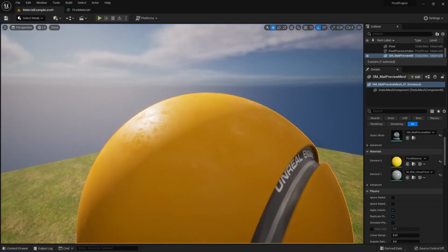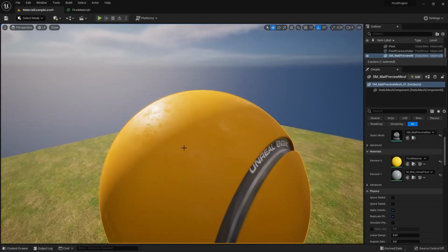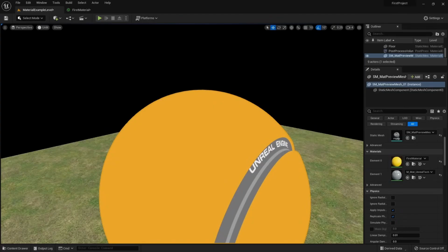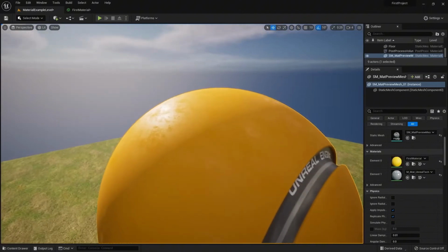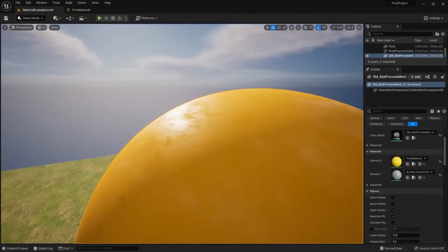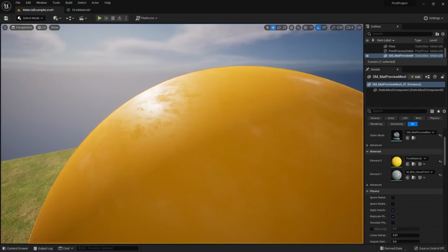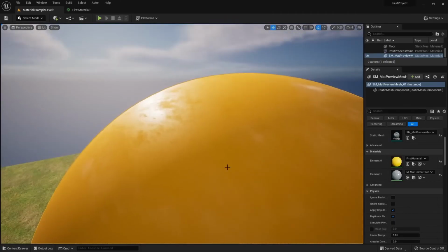At this point, let's switch up the colors. Since if I go into color mode by pressing Alt-3 for unlit, we can see that's still all one uniform color. Pressing Alt-4 to go back into lit mode, I want it where all the smudges are a different color that's a little bit more brown than orange to represent dirt.